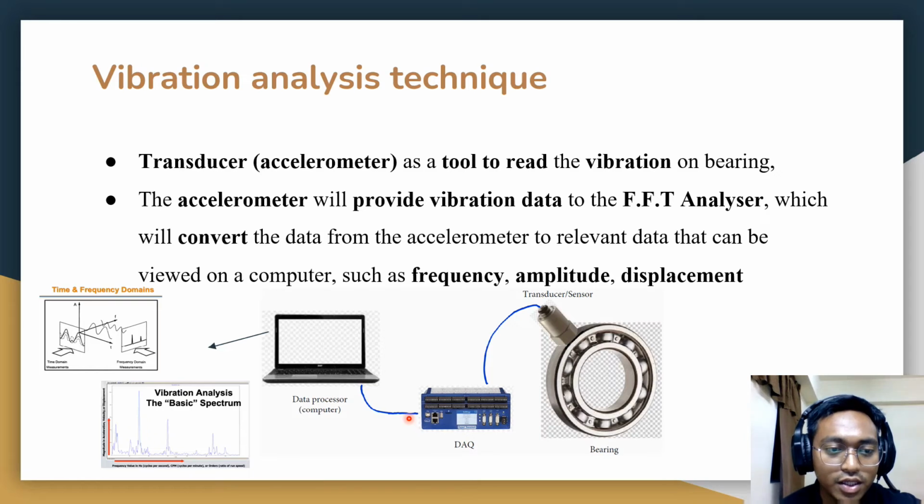Then we use a computer to convert the data from the accelerometer to relevant data, which is frequency, amplitude, or displacement.